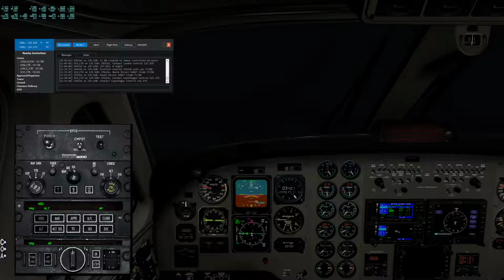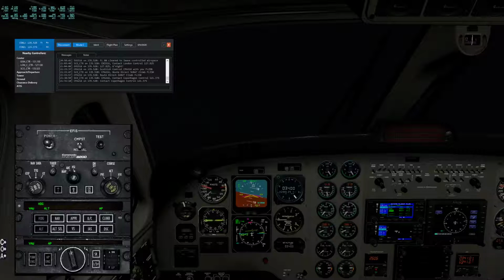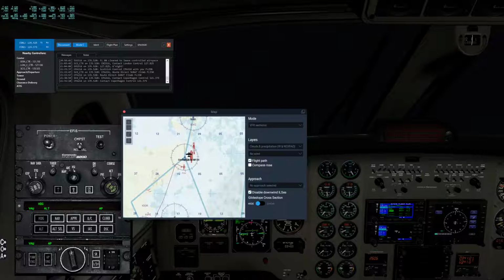And we don't turn in until the 315 radial. Again, that's marked on the procedure, the point where you want to start turning in. So this is actually quite a long arc to follow. I think with hindsight it would have definitely been more efficient to go to the hold, fly out for 1 minute, turn back in, and then fly out for 8, and we're on final. Base turn, final. Anyway, we're on the arc now.